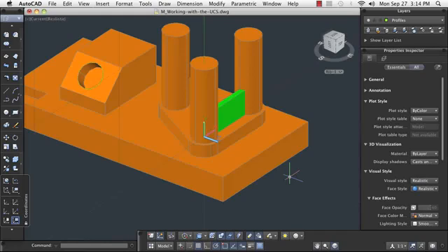Working in 3 dimensions requires manipulating the UCS on a regular basis. However, each time you change your UCS, you will be establishing the current X, Y, and Z directions in your mind, an essential part of designing in 3D.